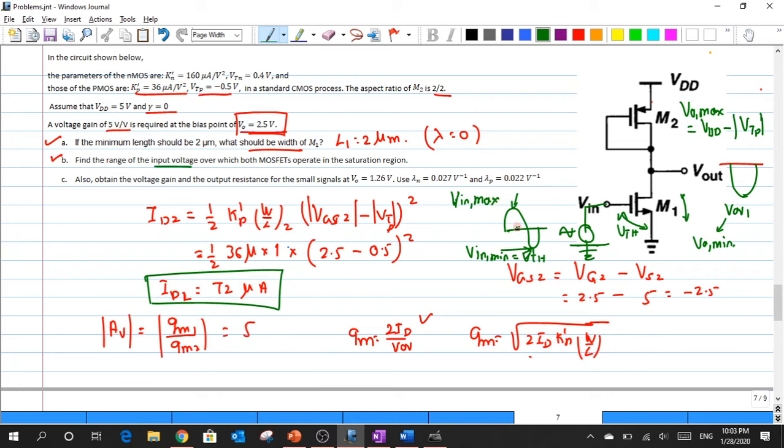Whenever there is a positive swing, my gate potential is raised up, due to which the drain potential is stepping down. Now there is a particular point where I could relate my VGS value with respect to my VDS value at the edge of saturation.